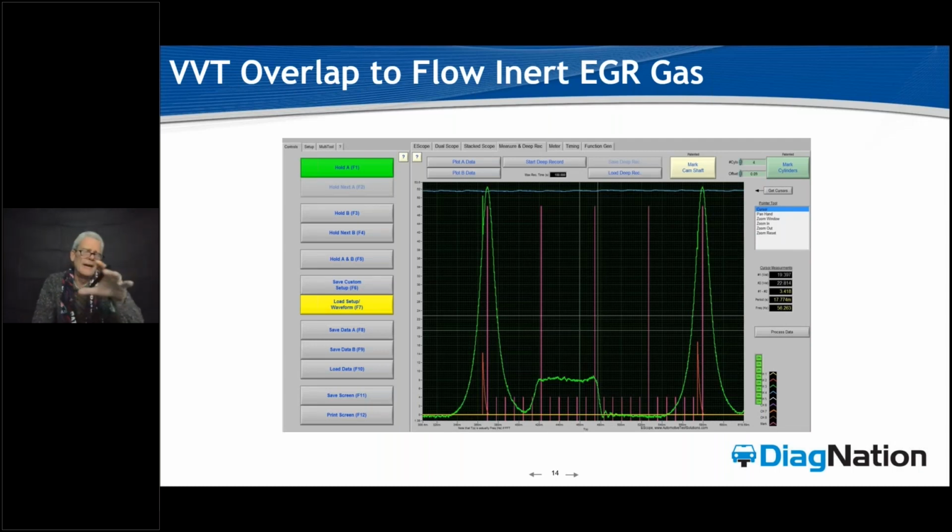So the other area that we really get a lot of problems in the depositing area is in the variable valve timing. We just had a Chrysler last week, a Jeep, that actually had a problem with the phaser loading with sludge. After the PCM would release the phaser to go back to its normal timing position, it was hitting a wall with that impacted sludge, wasn't returning, and it was setting trouble codes, and it was a little bit of a diagnostic issue for the shop.